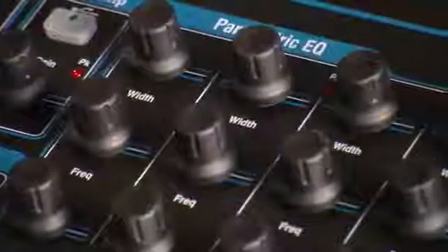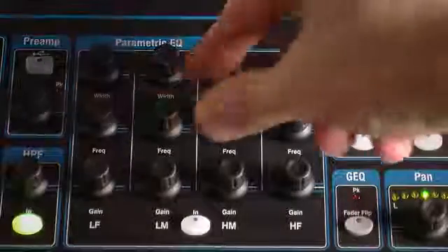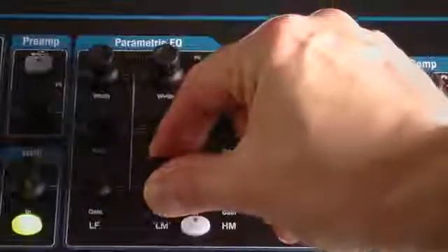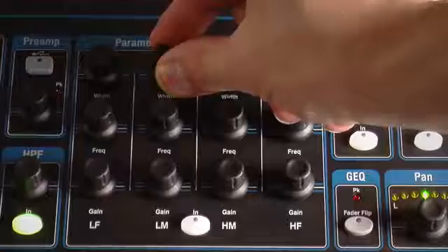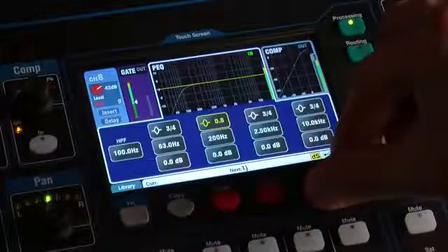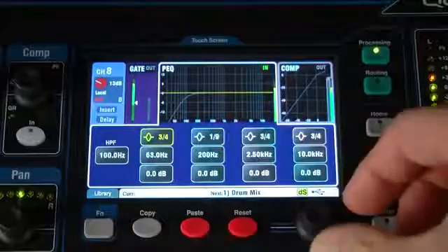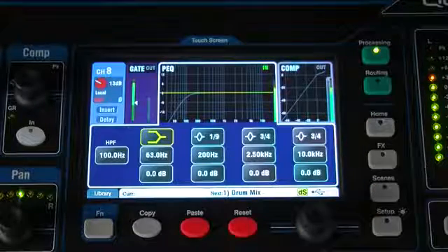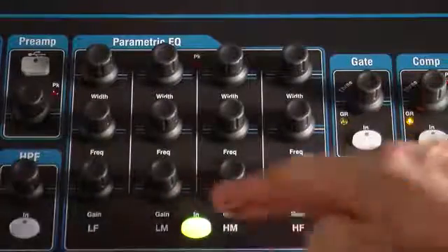The parametric equalizer allows tonal adjustment of the channel sound. Each of the 4 bands available provide 3 parameters that can be adjusted. The center point frequency you want to boost or cut, the amount of gain or reduction, and the width of the bell, which can be varied from a very wide 1.5 octaves to a very narrow 1/9 of an octave. Setting LF or HF to its widest position changes the band response to shelving. Experiment with the controls to hear their effect and toggle the PEQ in or out to compare the sound.